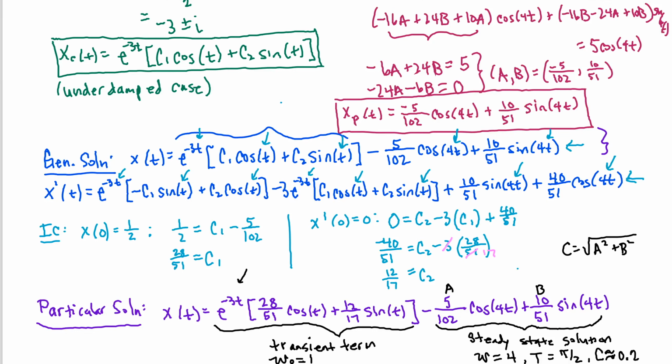So this is probably the most interesting case of driven motion with damping. We had our underdamped case in combination with not only damping but an external forcing function as a harmonic oscillator. Now, this completes our study of linear equations with constant coefficients, both homogeneous and non-homogeneous. We really focused on the spring mass application. Even though that's a very simple physical setup, it relates to all kinds of mechanical systems. In this section, you also learned about beats and resonance, which are universal in their application to mechanical systems.